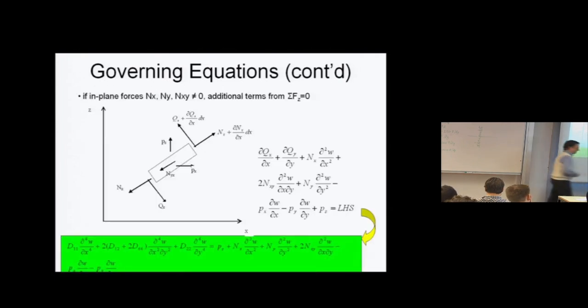And there's a variation of those equations if you're trying to do a buckling analysis, you have to include some kind of first-order effects. And briefly mentioned here is how you would do the force equilibrium in the Z direction. And the book has the complete derivation in much more detail. Basically, if you look at this equation at the bottom here, I have the D matrix with the derivatives of W, and those are the same.